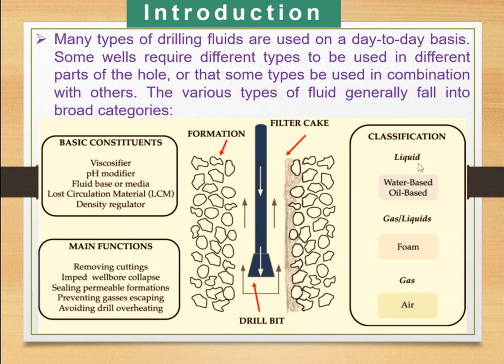Classification-wise, liquid based means water based and oil based, two types. Then gas or a gas plus liquid mixture, that is foam, only gas, only water, only air. Viscosity is more for liquid compared to gas. Gaseous fluids are required when formation pressure is much less than the borehole pressure.